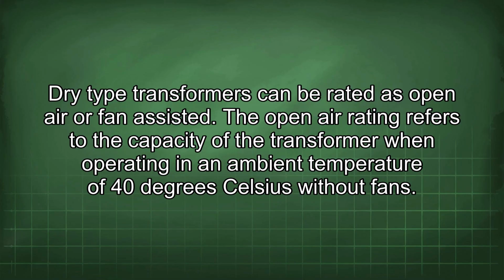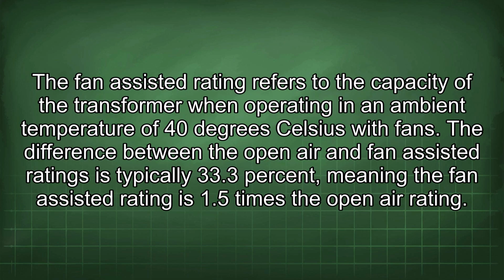Dry-type transformers can be rated as open-air or fan-assisted. The open-air rating refers to the capacity of the transformer when operating in an ambient temperature of 40 degrees Celsius without fans. The fan-assisted rating refers to the capacity of the transformer when operating in an ambient temperature of 40 degrees Celsius with fans. The difference between the open-air and fan-assisted ratings is typically 33.3%, meaning the fan-assisted rating is 1.5 times the open-air rating.